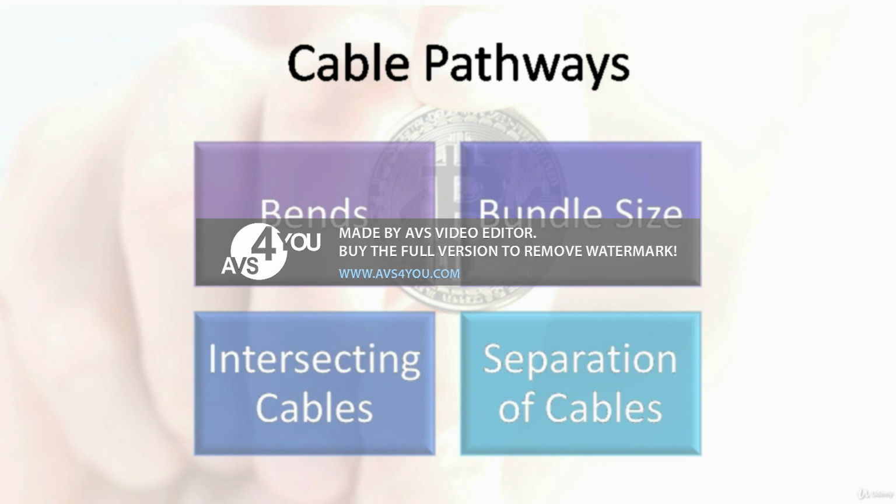Now, with bends, when designing the pathway or routes for your cables, you need to make sure that none of the bends are less than the bending radius set by the manufacturer. If the bends are too tight, the cable may become damaged. As for the bundle size, there is no limit as to how many cables you can bundle at the same time, but do keep in mind that the bigger the cable bundle, the harder it is to manage and maneuver. So put that in the back of your mind when you're pulling cables. The higher the number of cables in your bundle, the harder it is to pull.